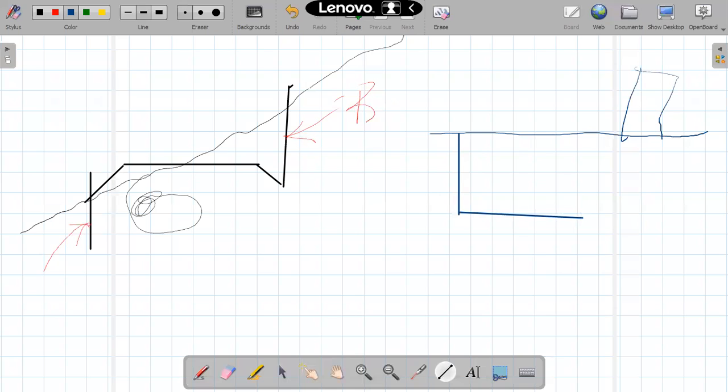I need this open space, maybe for parking purposes, or the basement portion may be used for some other purpose. Here I'll have to maintain the earth or these sides in vertical positions. So in this case, I'll be providing retaining walls.